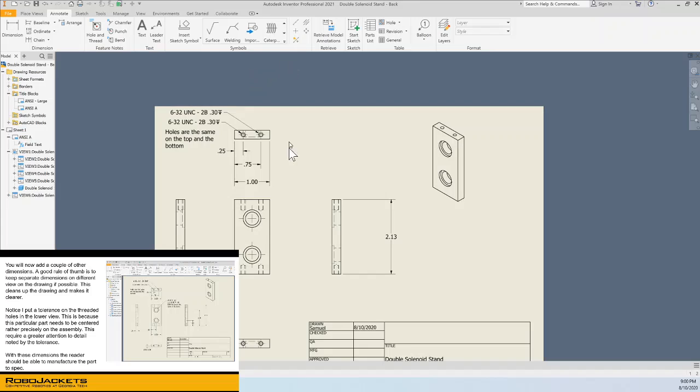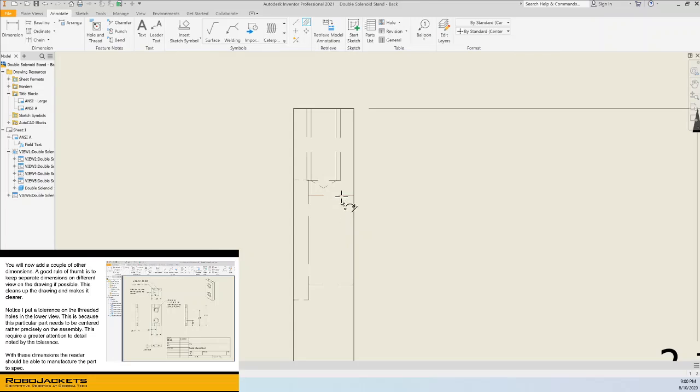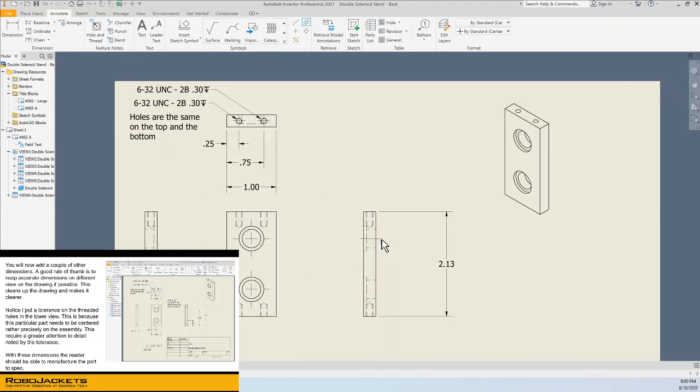And then, like I said, for holes from the side, you go over here to Centerline Bisector. And all that means is that when you click 2 lines, it'll create a center line in the middle, as if you're cutting in half, bisect. So we can go ahead and do that. And I won't do it on all of them.